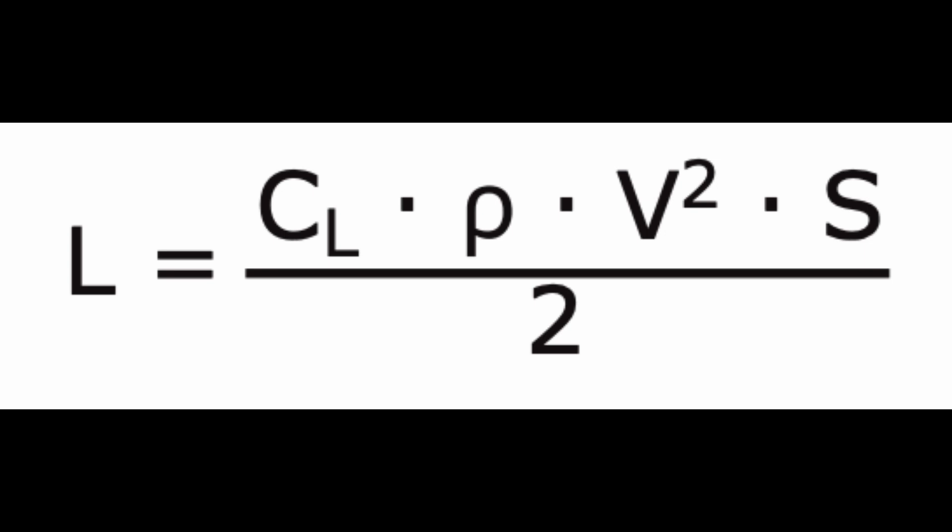When examining the equation, lift, L, is determined through the relationship of the air density, ρ, the airfoil velocity, v, the surface area of the wing, S, and the coefficient of lift, CL, for a given airfoil. Taking the equation further, one can see an aircraft could not continue to travel in level flight at a constant altitude and maintain the same AOA if the velocity is increased. The lift would increase and the aircraft would climb as a result of the increased lift force or speed up.